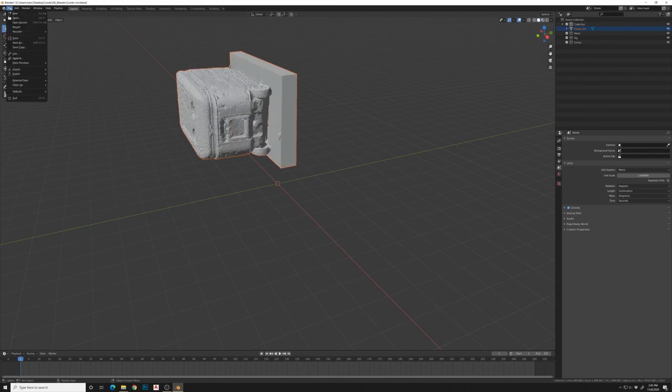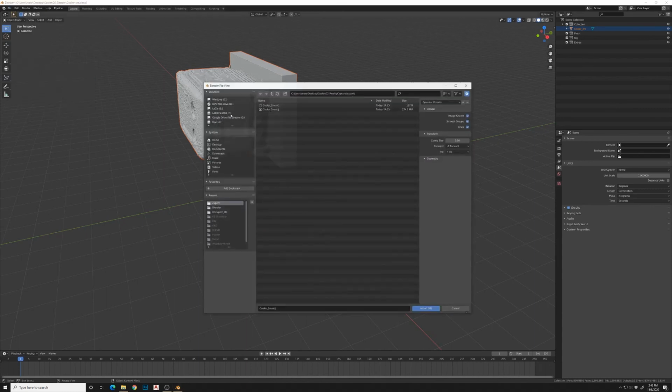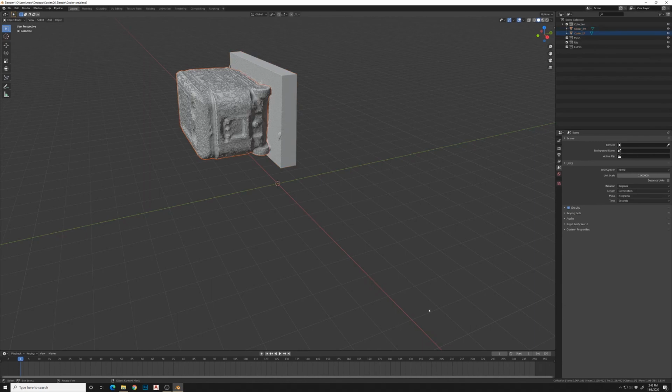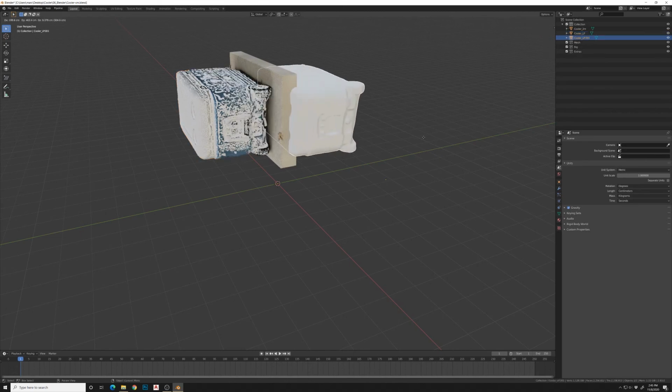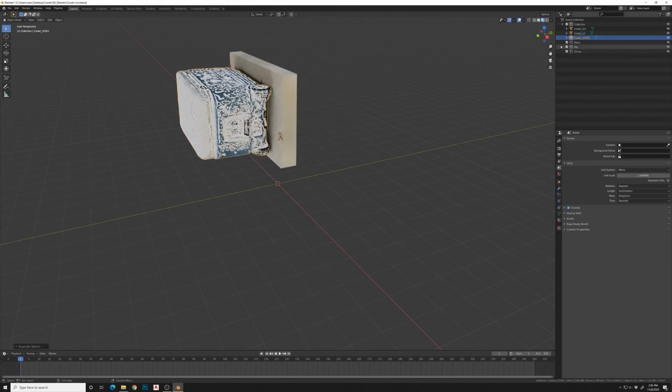So we're going to go File and import OBJ, and we're going to bring in our one from Mesh Mixer, and we'll do the LP. Import that. It should come exactly in the same place. You don't want to move these things. So we go to here, and we're going to take the cooler low poly and do a Shift D to duplicate, then escape.